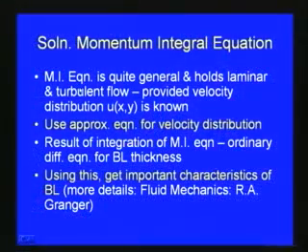So, we have to either put in some assumptions, or if we know some measured values of, say, the boundary layer thickness, the velocity, the wall shear stress, or the displacement thickness, then we can find out the other parameters. If one or two of the parameters are not known, then the remaining parameters can be found. So, the momentum integral equation is quite general and holds for laminar and turbulent flow.